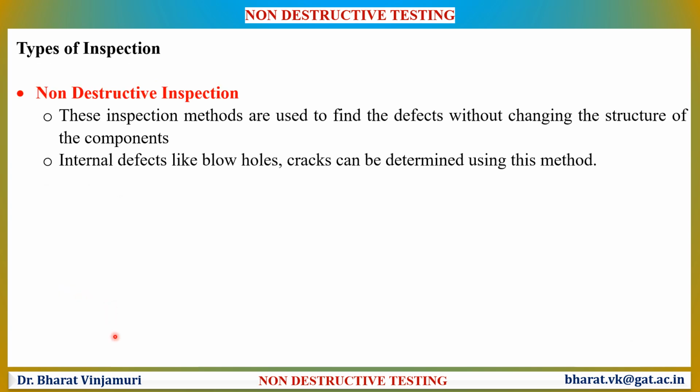The next important type of inspection technique is non-destructive testing, which is mainly employed to find the defects in the components without changing the structure of the components. Internal defects like blowholes and cracks can be determined using this method.